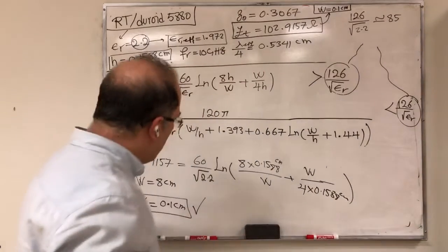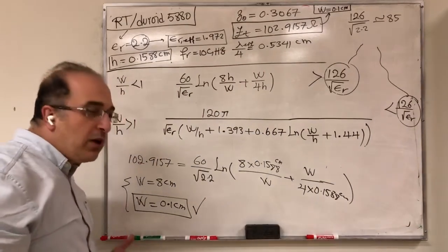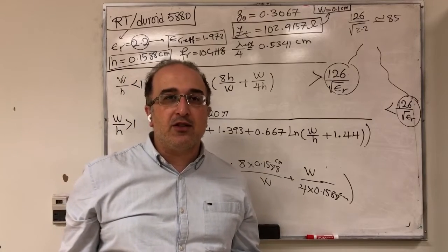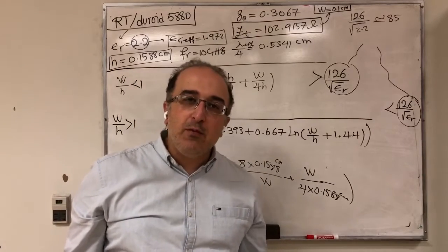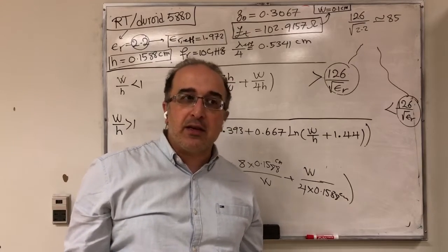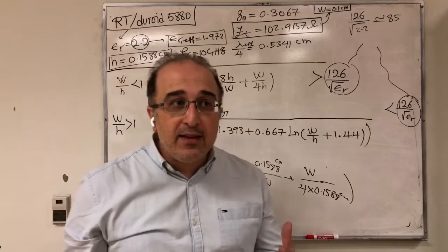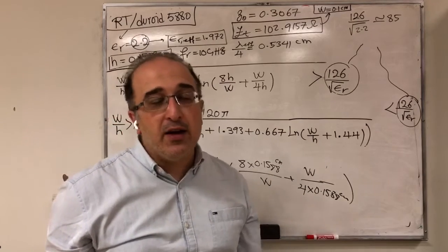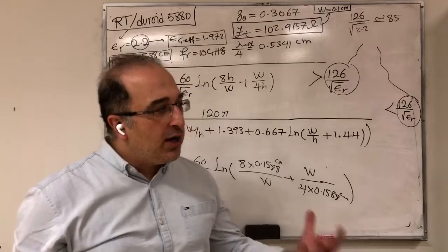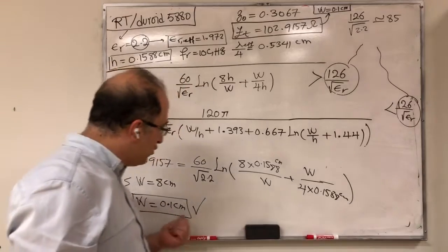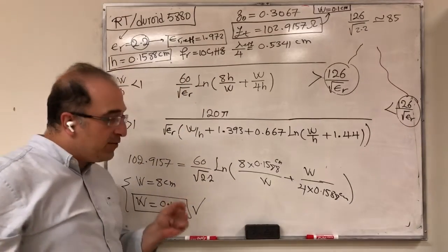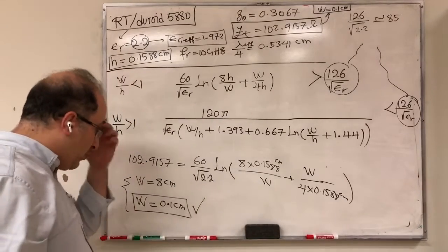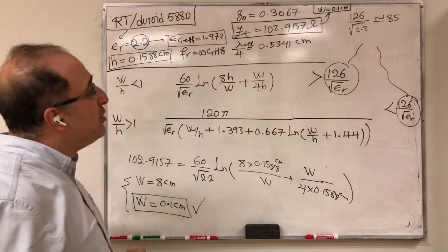So that we know the end result. And 0.1 centimeter can actually give you problem in terms of fabrication. So this is the limitation of this quarter wavelength transformer, that you may need higher fabrication accuracy that you might not have accessible to yourself. Consider that you are now creating a line with a width which is extremely small. So that's one thing to keep in mind.